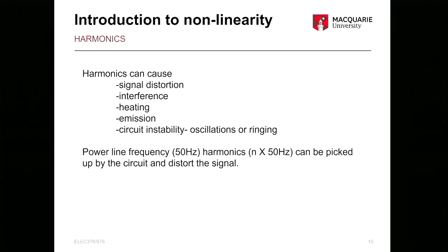But because you are generating not just 10 kilohertz, if your system is nonlinear, you will be creating multiple frequencies of 10 kilohertz, and you will be creating 40, 50, 60, 100 kilohertz. Not intentionally, but without your knowledge, you might be creating all these frequencies, and other equipment will get affected by your radiation of these frequencies.